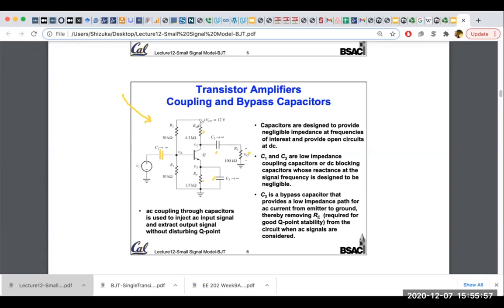First, we look at the DC voltage. There is a cap here, which at DC means steady state eventually, because it settles quickly. The cap gets a voltage on it, so it becomes an open circuit. The reason there is a cap here is that we don't want the DC signal to go this way. We want to capture it because we want to put a bias on this transistor.